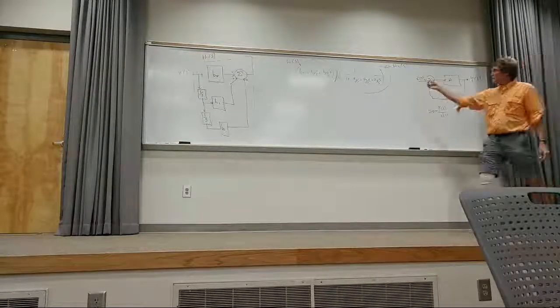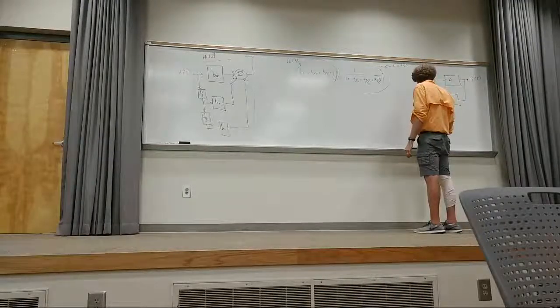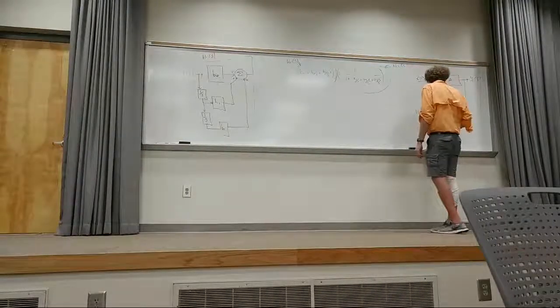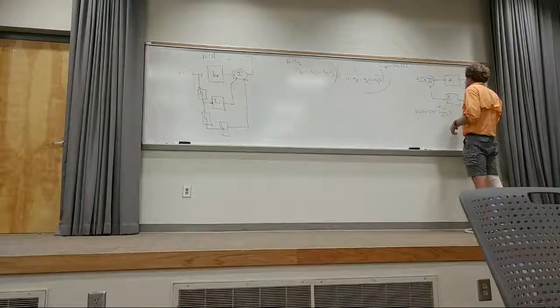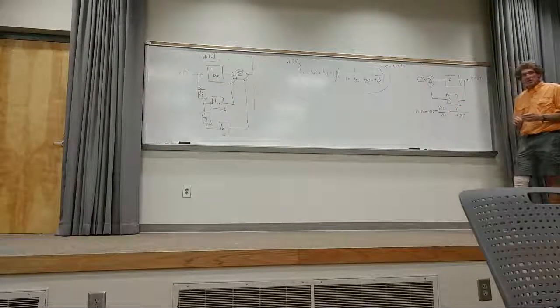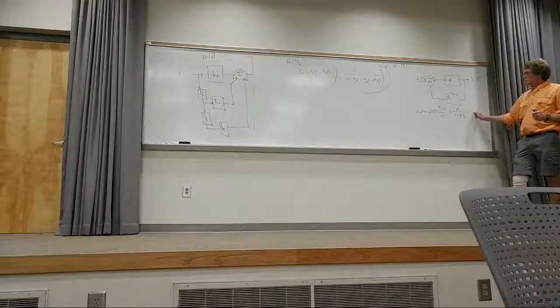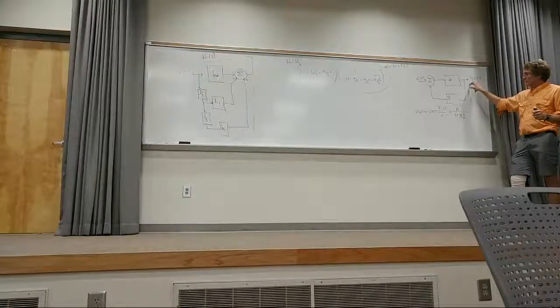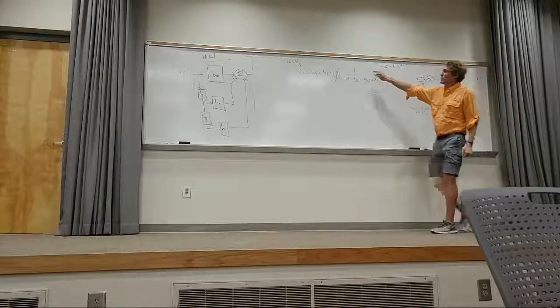So by inspection, if we're trying to equate H2 of S to this right here, which is going to be A over 1 plus AB. Does everybody see what I'm doing here? This is what we just figured out, the input-output relationship of this circuitry, right? We're going to make A equal to 1, because there's a 1 there.